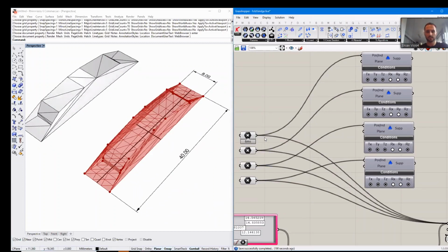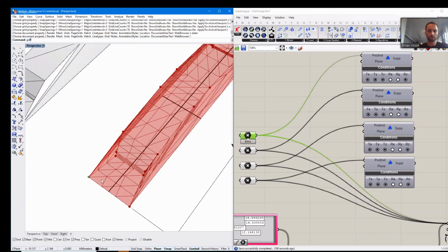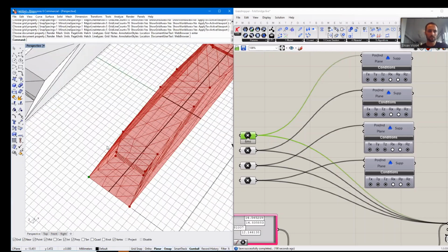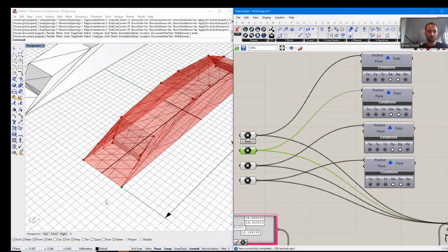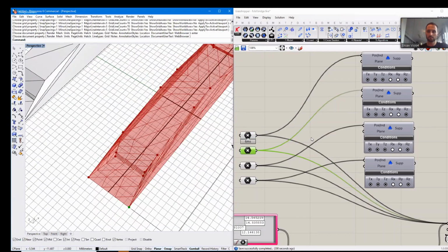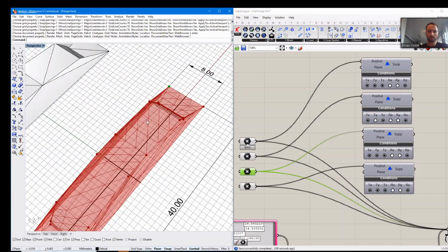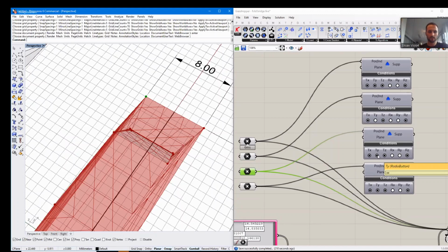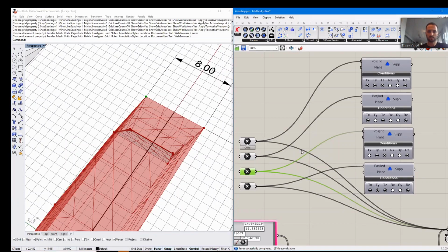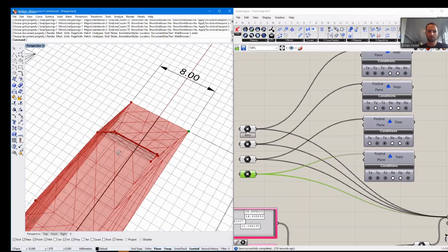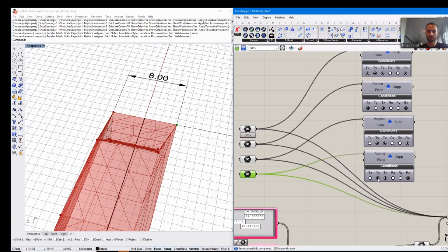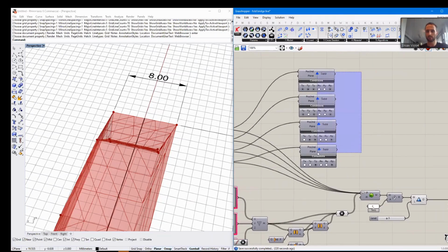This goes into structural mechanics now. So at this point, we're going to fix in all directions. The second point here, all 4 points will be supported in Z direction. This one will be free in Y direction. This one over here will be free in X direction, and this one will be free again in X direction and Y direction. So now the structure is supported statically determinate.